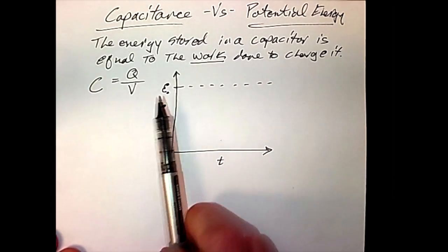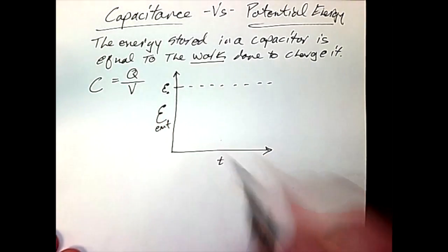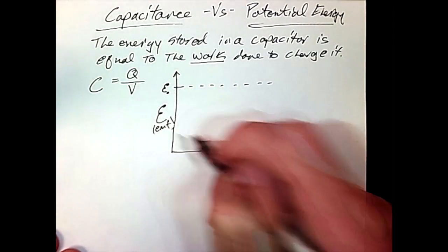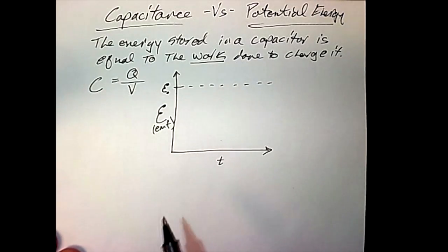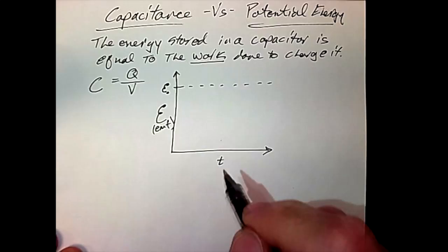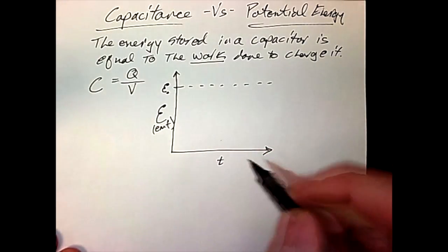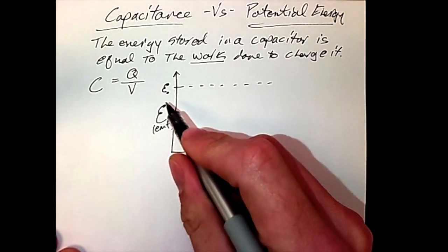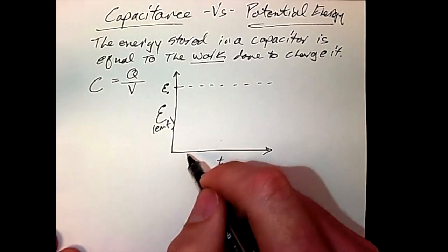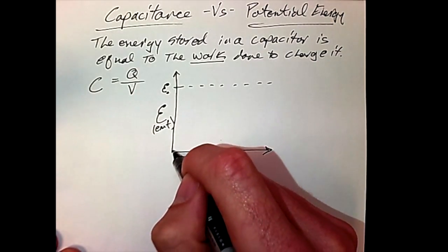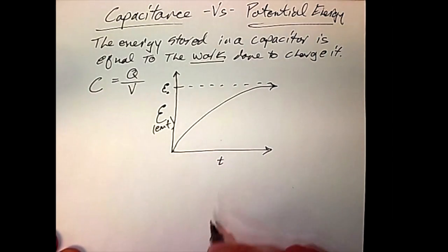If we apply an EMF, an electromotive force, or an ideal voltage to an RC circuit, a circuit that contains both a resistor of some kind and a capacitor for storing charge, you'll see that as current flows through the circuit, the voltage on the capacitor will increase. However, it doesn't increase linearly. It increases exponentially, with an asymptotic reaching of the ideal value near the top.